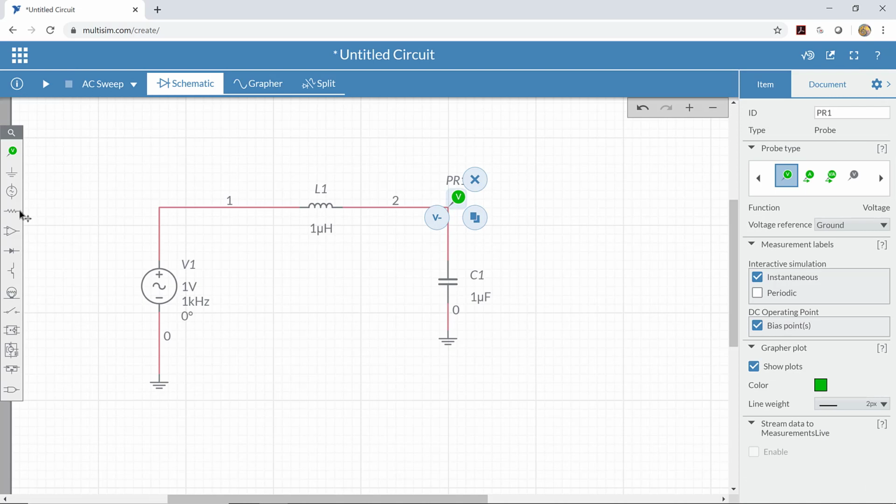And most of the high frequencies get blocked by the inductor. And any high frequencies that do make it out through the inductor also go through the capacitor and get down to ground. So this is kind of a double whammy. The two components are working together to reject high frequencies and allow those low frequencies to go through. So this is a low-pass filter. If you switched the position of the inductor and the capacitor, then you would make a high-pass filter.